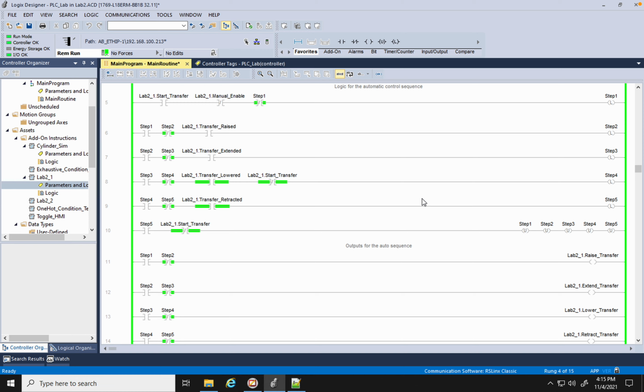We can use a simple bit latch sequence to control the automatic function of this machine, but at a mode level, it's not sequential. So we need to split those two components of the program apart and use the state machine to control the mode, and then use the bit latch sequence to control the automatic operation.